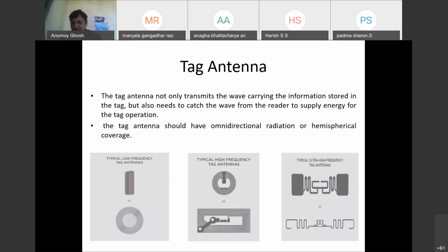That means to conjugate match this chipset with the antenna, I have to introduce a capacitive element so that it can compensate the inductive element of the chipset. The capacitive element and the inductive element will cancel each other out, and I will get only the resistive element, which is the fundamental of an AC resonance circuit. That is why these kinds of meanders are sometimes placed above the chipset to conjugate match the chipset impedance.